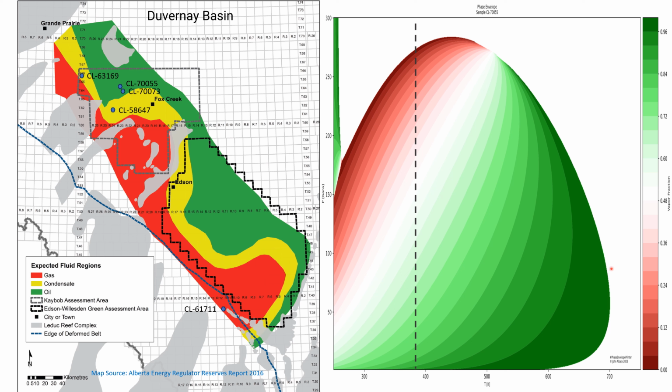As compared to the previous one, again, we have a higher C7+ content here, and bubble points going down, and yes, around 175, we also see this behavior, this unstable region shooting upwards almost asymptotically. And more interestingly, this fluid exhibits a secondary critical point here right after the tail starts forming. See how those isochores converge toward this point.